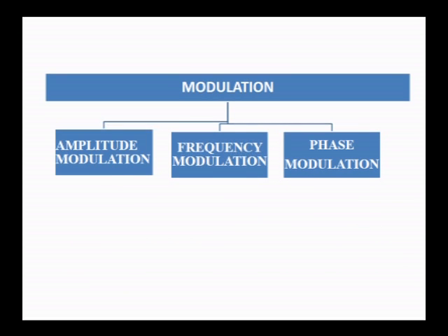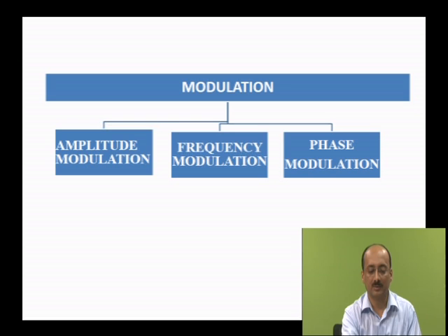And the process of modulation is very vital for communication. Without modulation, we cannot send waves. Ordinarily, when you have a message signal, it is a low frequency signal. If you are sending that, a lot of energy loss will be there, and therefore you need to modulate. If you just send those waves without modulation, impractical antenna lengths will be there, which extend up to several kilometers. Therefore, modulation is very much essential.